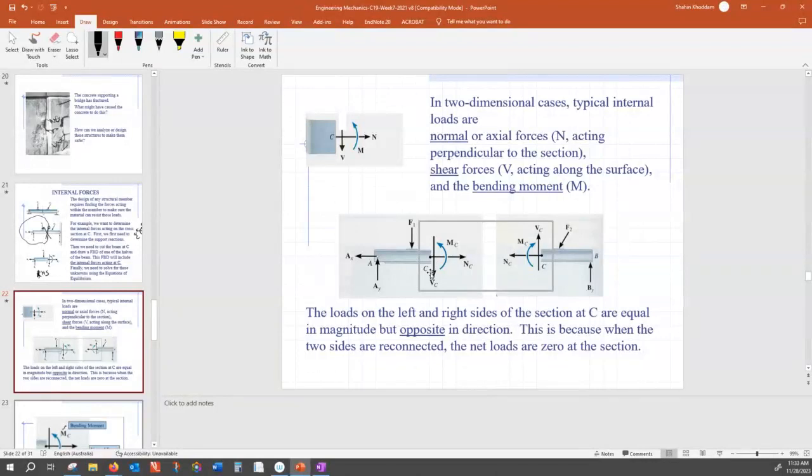Why? I'll give you a joke to remember this easily. That joke is, it's positive to laugh. It's negative to cry. Okay? So these types of loads make my beam laugh. My beam laughs. This is positive bending. These types of things are making my beam cry.